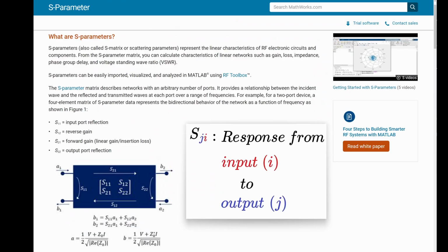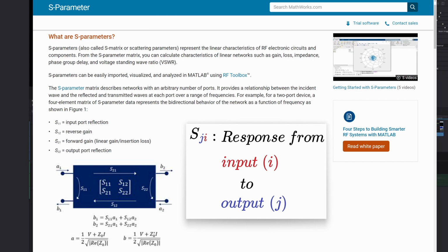I'm an applications engineer with the high-speed data converters team at Texas Instruments. As we know, VNAs are used to evaluate or analyze a system or network. This piece of equipment works by providing an excitation signal into a user-specified port or net of a system and measuring the response at another user-specified port of the same system, all while varying the frequency of the excitation signal to produce what are known as S parameters. These S parameters represent the amount of power passable from any excitation port I to the measured port J.